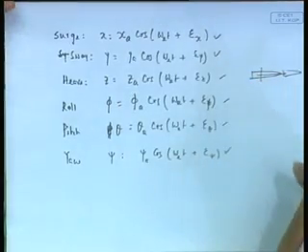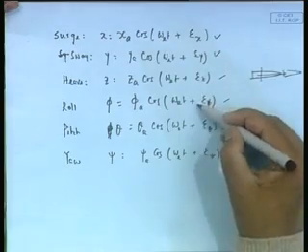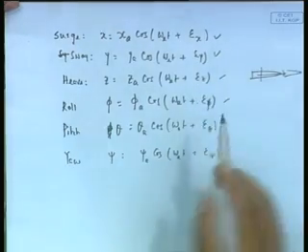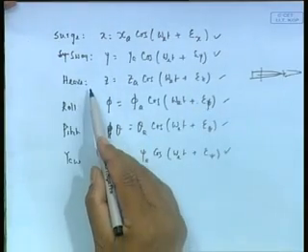On the other hand, it is heave, roll and pitch, where if I for example push the body down, then it will try to come up and there is an oscillation, and as you know, if there is a restoring force, then there is a chance of resonance. We will come to that subsequently. So, the important modes of motion for us become these three.